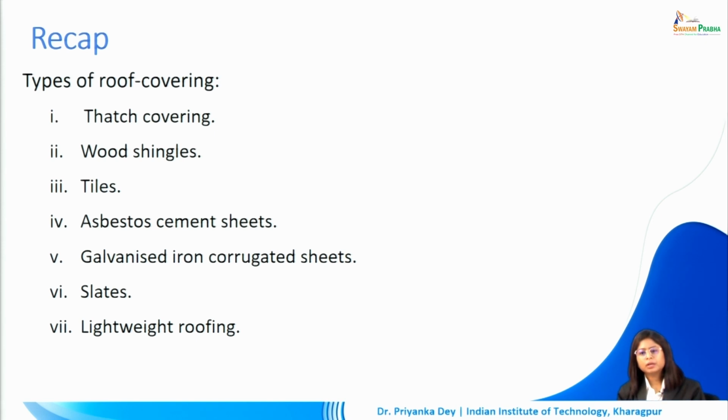They have the possibility to reduce the overall weight on the structure significantly and have restrictions with respect to the amount of load that they can take. Now, while finishing these types of sheet roofings, we can use stone chippings along with bitumen, etc. to ensure that the solar reflectivity is maintained, and we can reduce the amount of heat that the structure is being exposed to. So these were the different types of roof coverings that we can apply to our pitch roofs, which brings us to the end of this module on roof.